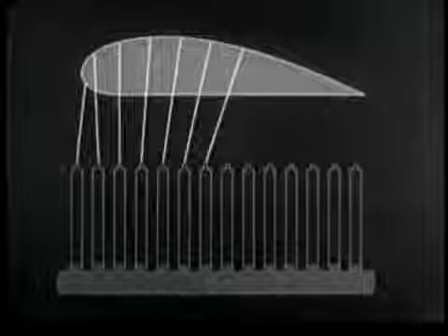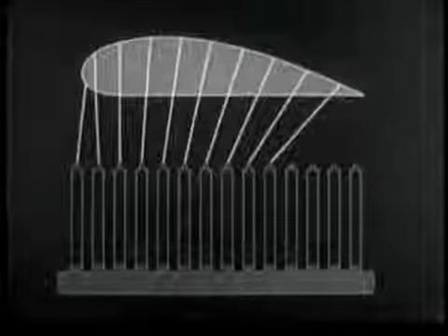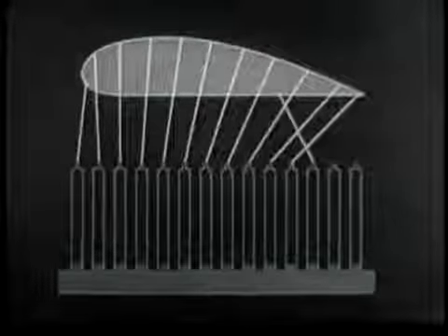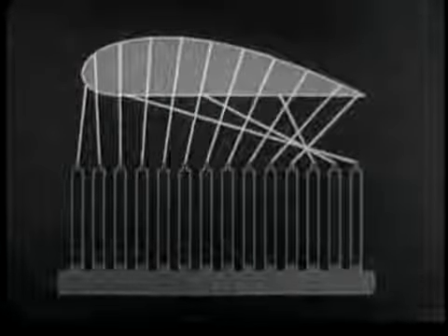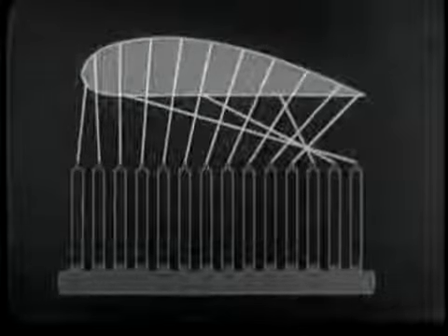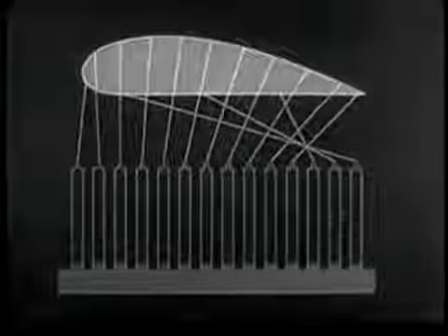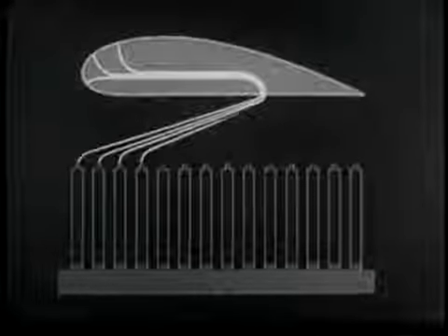The majority of these test points are located on the leading edge and upper surface. Relatively few are placed on the lower surface. Of course, this is only a schematic representation of the connection. In actual practice, tubes run from the manometers through an opening and inside of the airfoil to the test points.